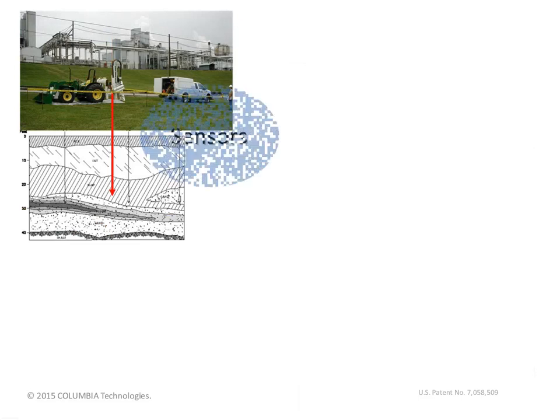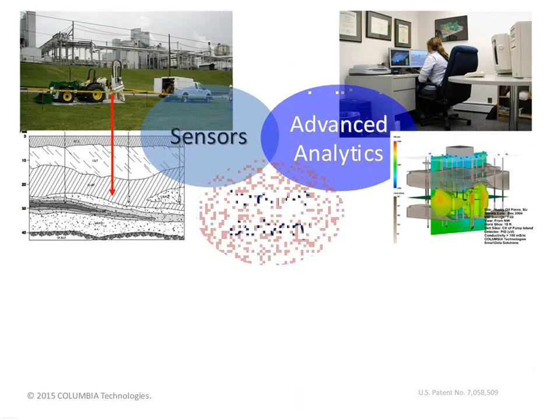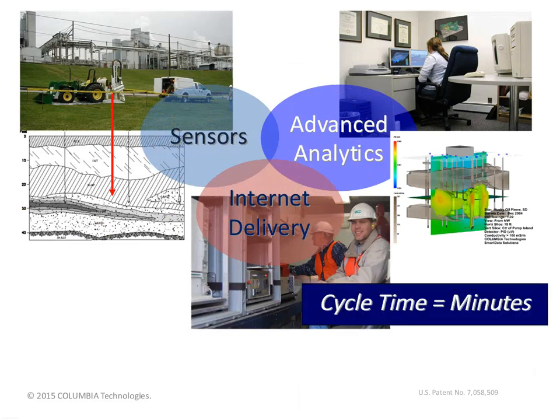This is a slide that basically says, with the direct sensing world, in the high-resolution world, we're able to drive sensors in the ground with any number of types of drilling systems and directly sense soil, water, chemical, physical parameters in high resolution, and that's generally about 20 times a foot, as a rough number. And we're going to see that information immediately in the field and be able to get a feeling for what depths and what soil structures, what permeabilities, and what contaminants we're seeing within the first few hours of being on site.